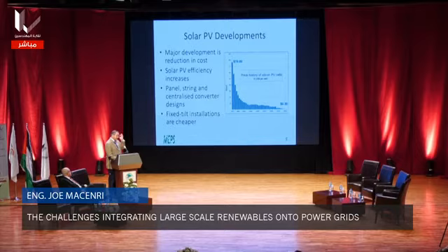The monocrystalline PV is the best PV technology, and they're getting up at 23–24% now, which is a very good efficiency rate. But the polysilicon, which is a cheaper technology, is getting very good as well, and it's following behind the monocrystalline by only about 3–4%. So they're getting up to 20% efficiency on the polycrystalline panels now.